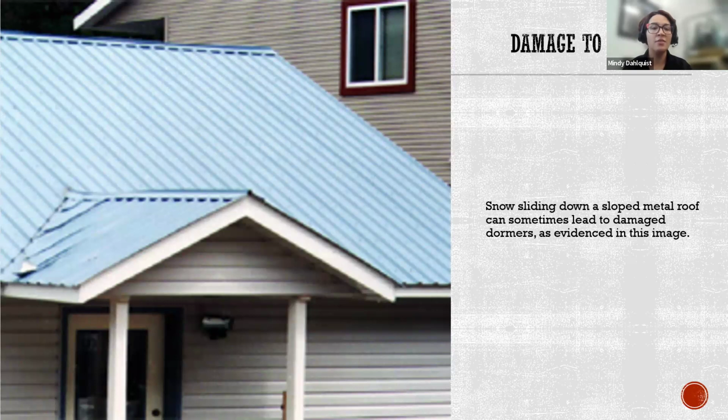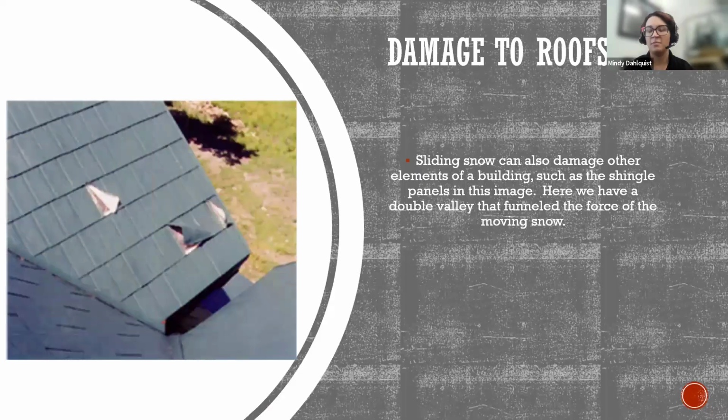So other things that can occur when the snow does move on the roof are going to be much less serious than something like that, but can definitely cause headaches and issues down the road within your homes or your buildings. So the sliding snow down this roof has just damaged this dormer. You take the force of that snow, and it causes some issues as that weight and the force of the moving snow comes into contact with these materials. This is also a double valley, so certain design functions of a home or building can also cause some concerns down the road if that snow does decide to move.